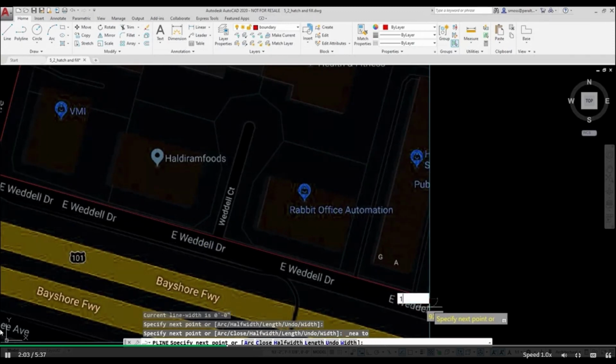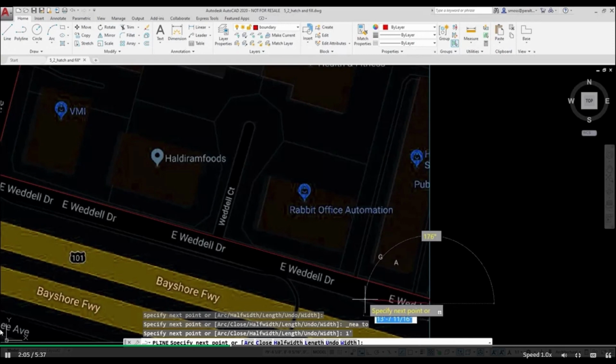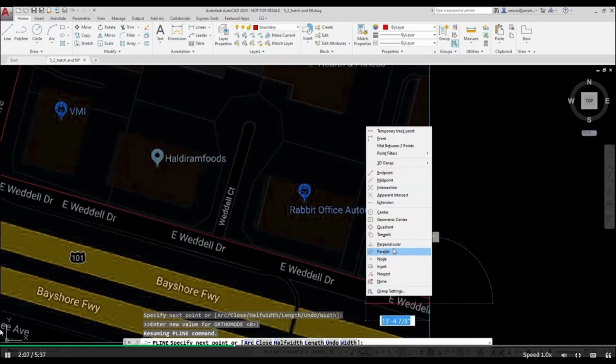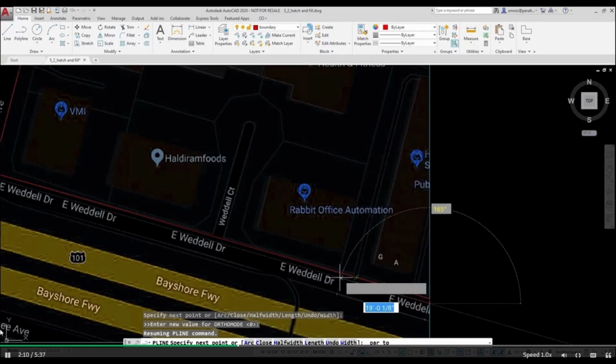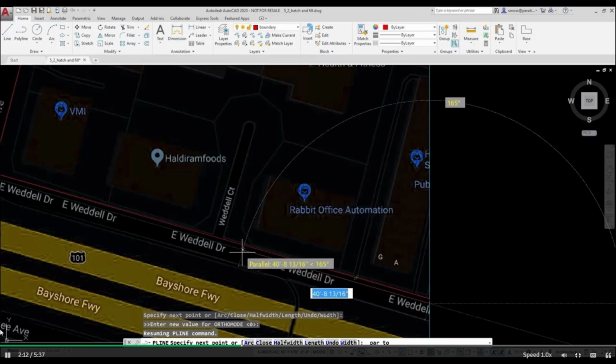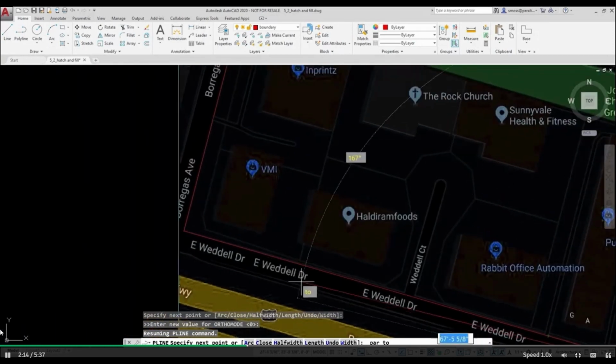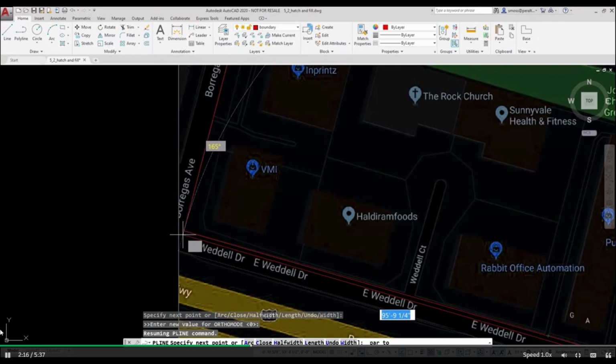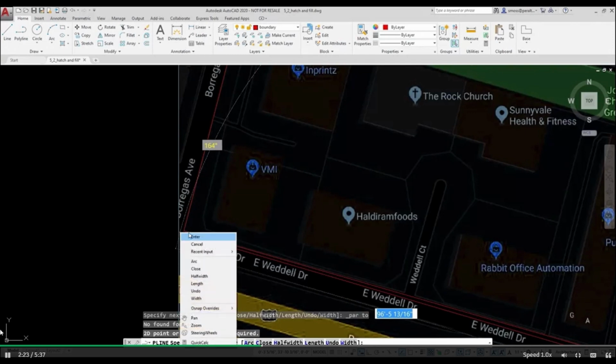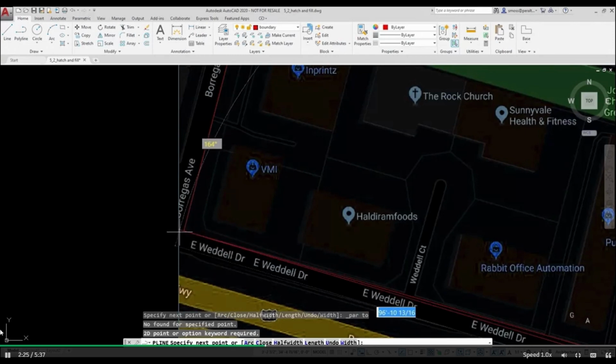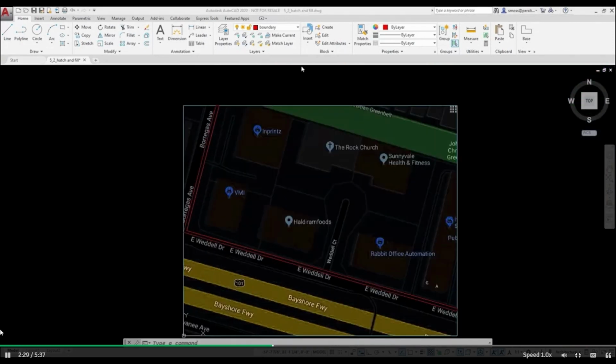I can use the Trim tool to clean up any overextending lines or use multi-grips to remove any unnecessary vertices. It takes a few minutes to create the polyline that I'm going to use as the boundary for my hatch. Once my boundary is placed, I can add the hatch. I switch to the hatch layer using the layer drop-down list on the Layers panel.